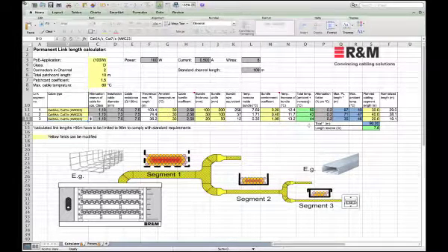So we have the temperatures at the right level, and we have some reserve here as well. So the result of this planning would be, if I want to make sure that 4-pair PoE would run in the future, I start planning my installation today not with a Cat5 cable but with a Cat6 cable, and use that to build up my installation.